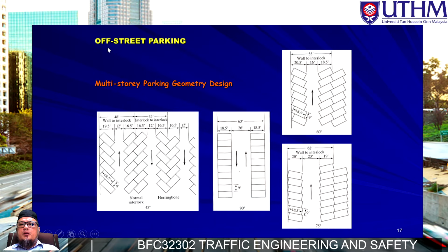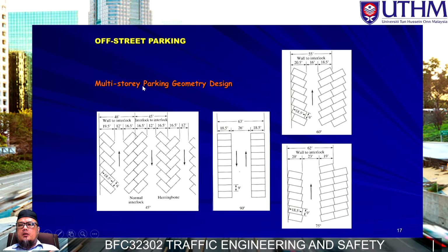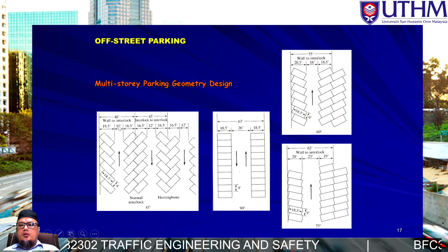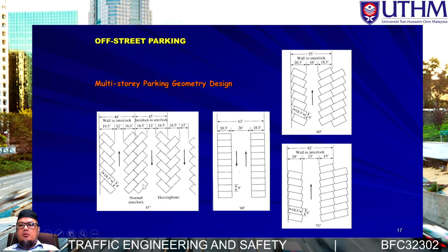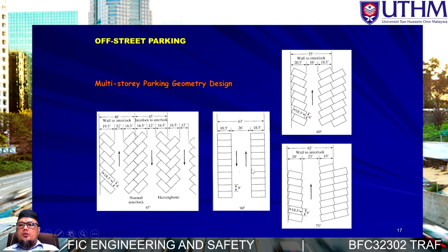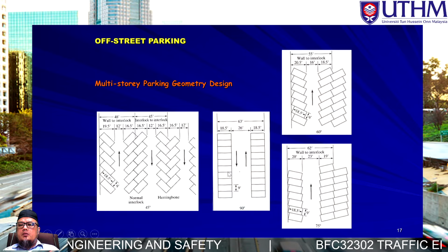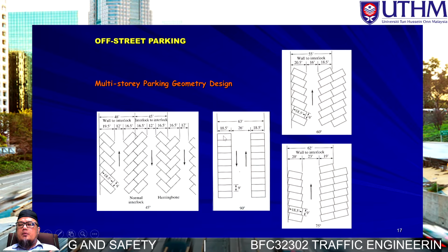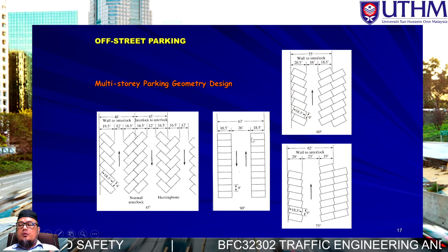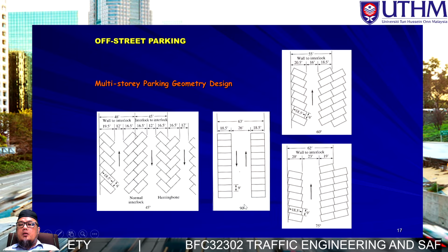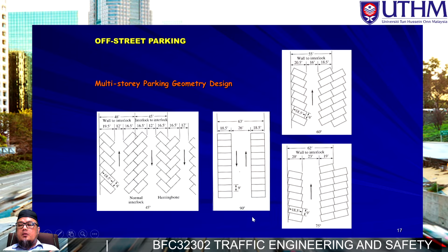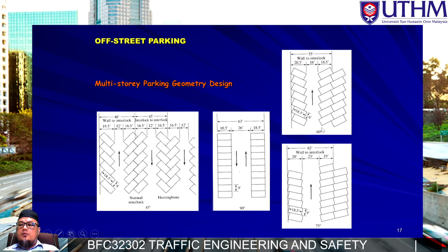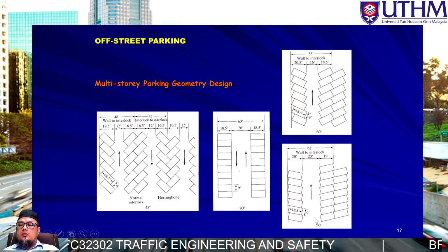Okay, this is the typical off-street parking in terms of thematic design, especially for multi-story parking. They have an interlock type of parking. They also have 90 degrees, which is considered vertical, this one is 45 degrees, and others can be designed as 60 or 70 degrees.